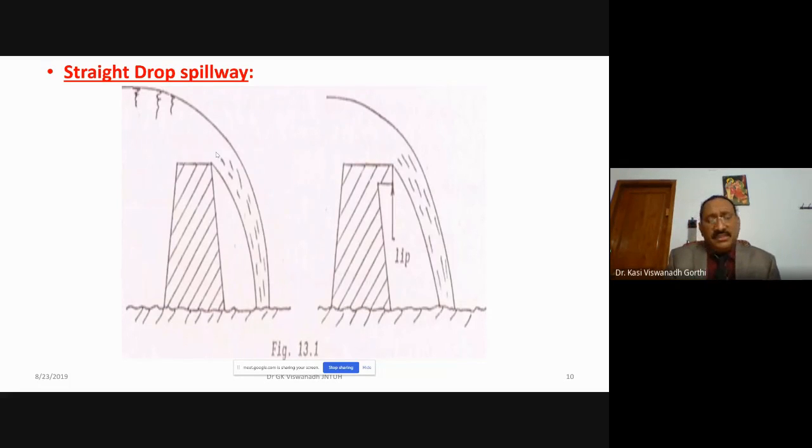But the disadvantage in this is, as we have seen in our second year fluid mechanics, there would be a problem when the water is flowing continuously to the downstream portion like this. In this portion, the pressure drops below the atmospheric pressure. Because of this, the nappe will always have a tendency to directly connect to the downstream face of the weir wall, leading to excessive forces and failure of the weir. So to avoid this, ventilating the weir is very, very important. In second year fluid mechanics, you must have studied the ventilation of weirs.